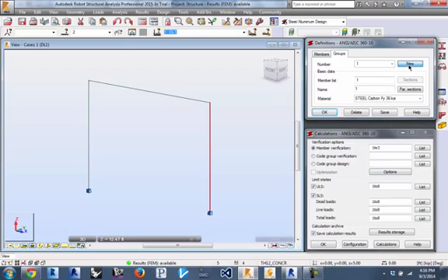So I'm going to say I want a new group. I'm just going to leave it number 1. The way we select the members in the list, I'm just going to highlight the number 1 in the member list, and then just Windows select over these. And you'll see how the information is input. So it's a 1 space 2.